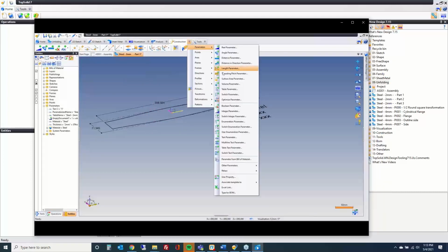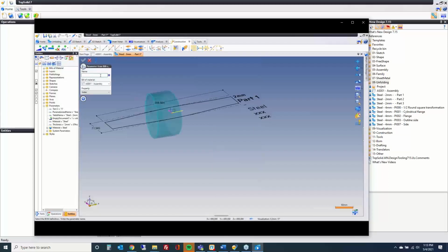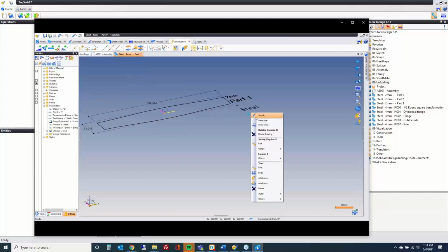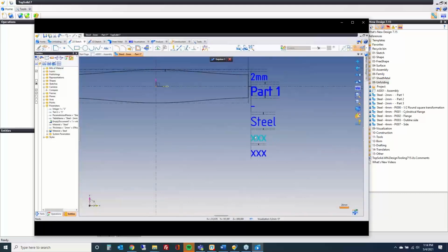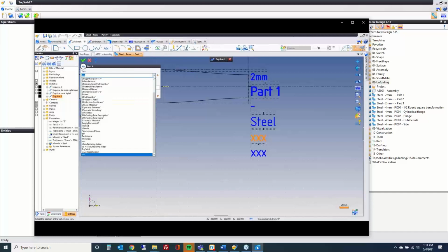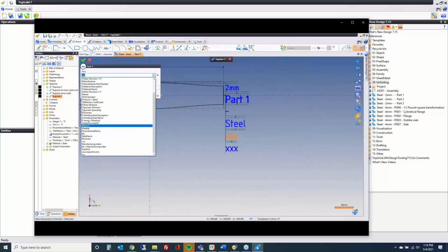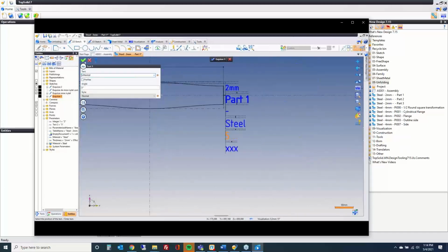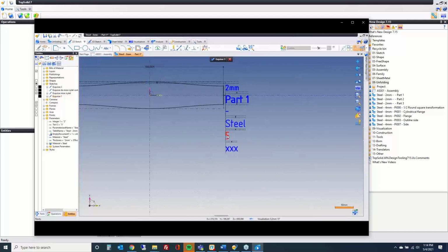We're going to make 2 more of these. Parameter from bill of materials. This one's just going to be quantity. Okay, and we're going to make 1 more. Oh, nope, sorry, we're just making 2, sorry. And here, we're now going to pass those parameters into the text that we have for this flat pattern. So you can see we just called it from the list. There it is. Now, we'll do the same thing down here with quantity.